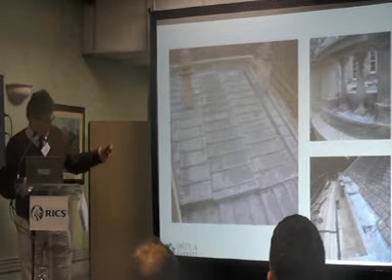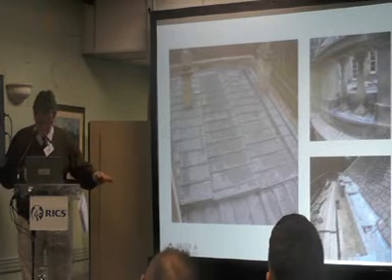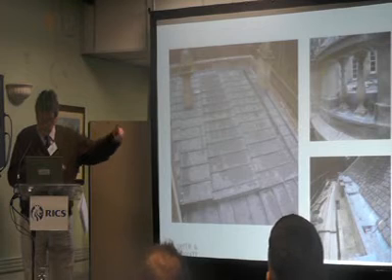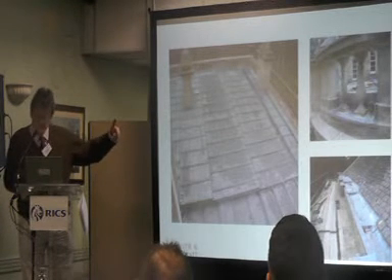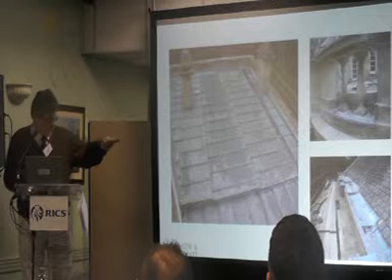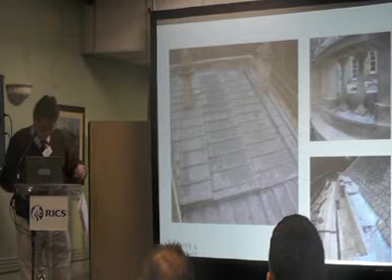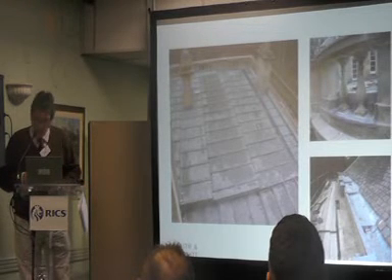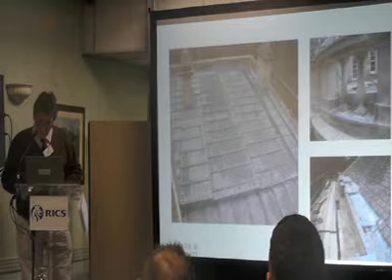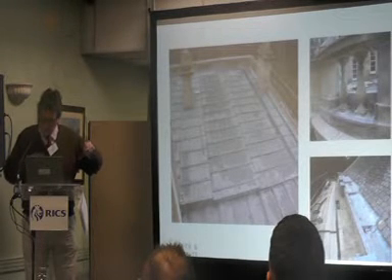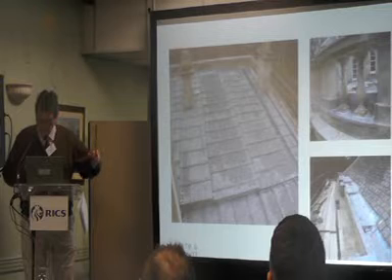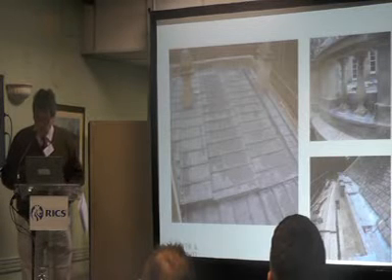This picture was taken, the main picture was taken before the lead had settled, so you can still see where it was rolled out. You can see the little bits of water there, and you'd think, right, that's not laid at 3 degrees, but it is. It's just that it's going to take a little while for the lead to just settle down. If your bays are too long, your lead will expand and contract, and it will wrinkle and stretch and wrinkle and stretch until it fatigues through, and obviously it'll let water through.